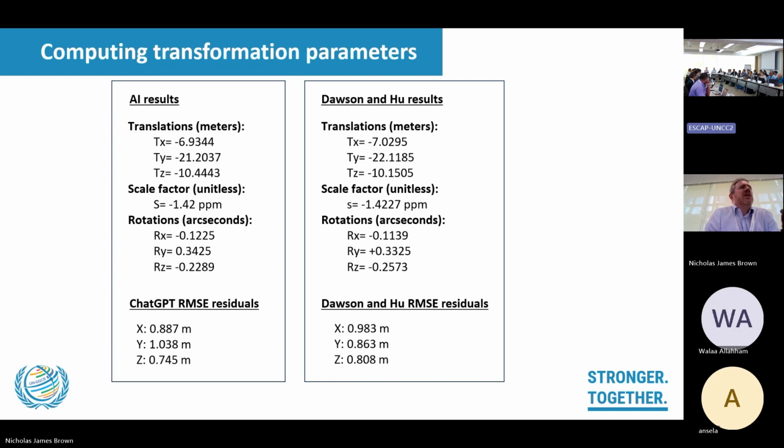So you're saying you use the ITRF ellipsoidal height as the ellipsoidal height in the old system. So you're assuming that the ellipsoidal height was the same. Is that what you're saying? Sorry, perhaps I didn't explain that well. We assumed that those points were ellipsoid heights without any geoid model.